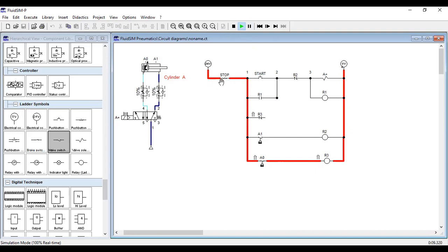Try to look at AO: it is activated or triggered, so activating R3. When R3 is activated, actually R3 here is closed. So that is why the current flows, from positive through R3 going to A plus, thereby making the system start by itself automatically.